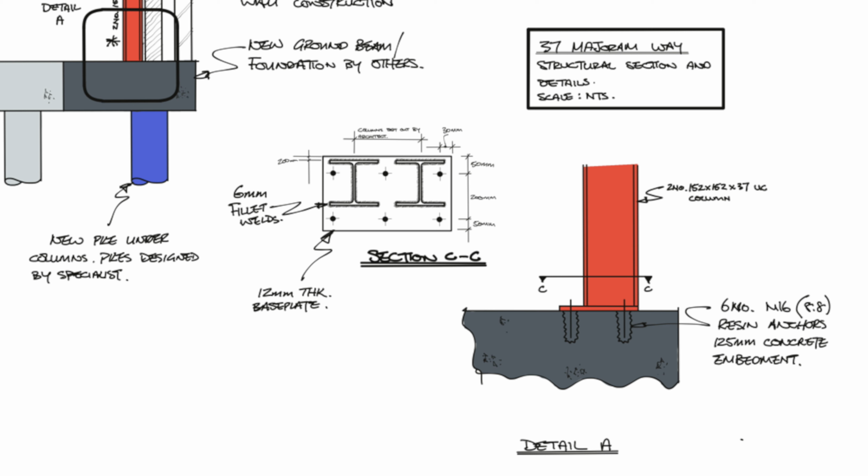What I've done is just blown up that little section, shown where my resin anchors are going to go, and also I've taken a section through the top of the base plate so that you can see exactly where the bolts are going to go on plan.